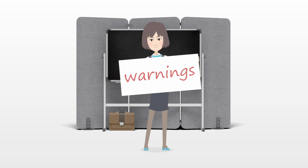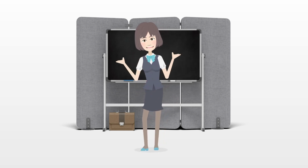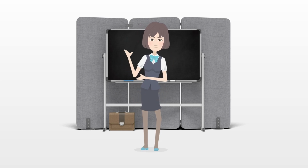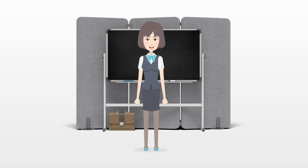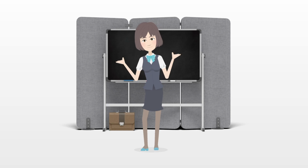Warnings. Wear gloves, cover your skin, wear safety glasses, wear rubber boots if you have to stand in it. Some people have very sensitive skin and react badly to cement. Concrete splashed in the eyes is no fun either. Concrete will also dry out leather boots and shorten their lifespan.